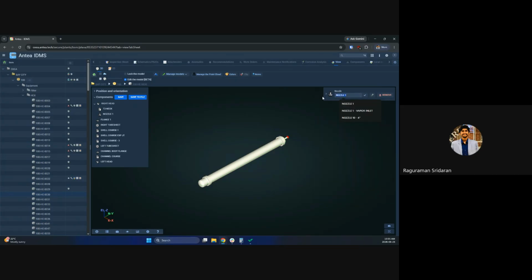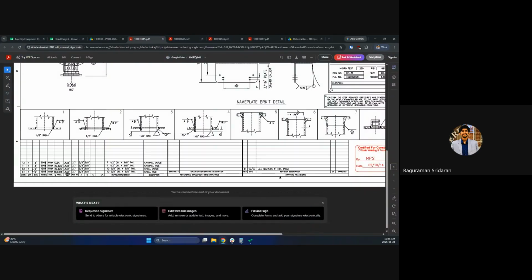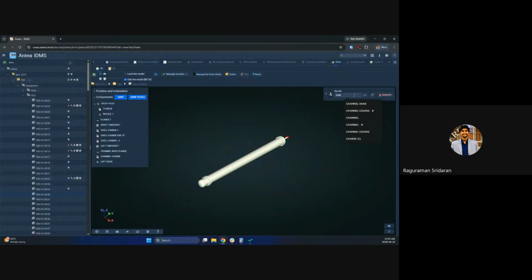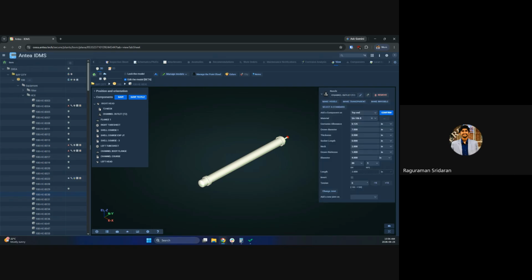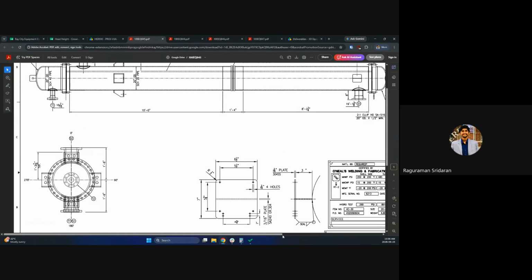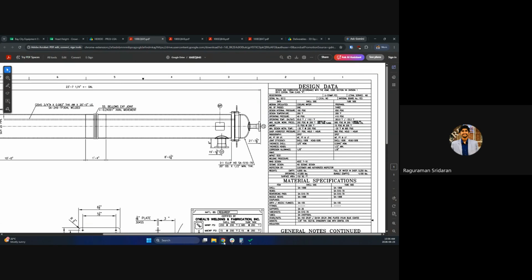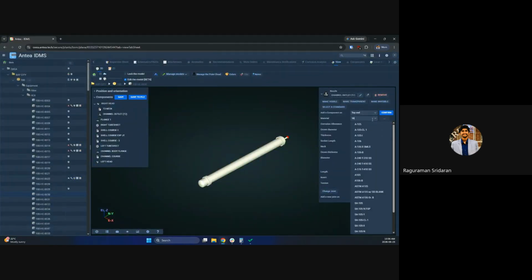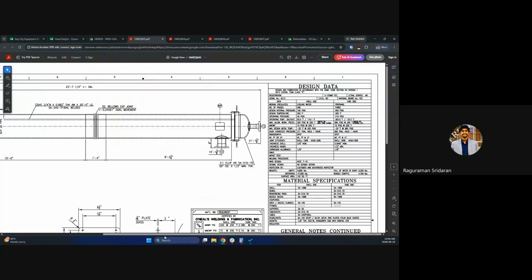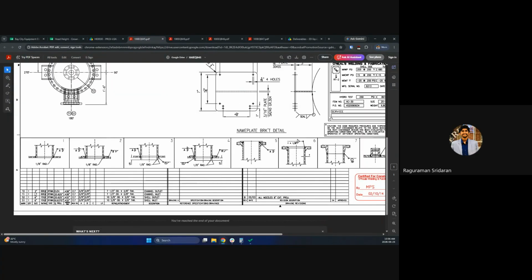We come here, we try to add the name of the T2. So the T2 is actually channel outlet. So I say that here, channel outlet T2. And now we will try to find the material. So it should be here, say 105. And select the standard from here. So let's say, for example, this is 3-inch 600 raised face weld neck.